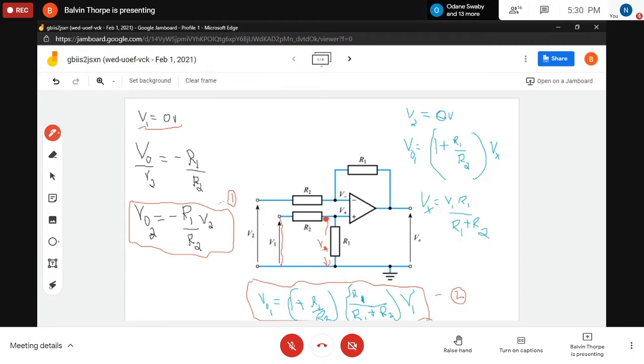We have looked at the inverting amplifier already. And if you can recall, the inverting amplifier's output voltage would be equation 1, where V2 is what's going in. The gain of an inverting amplifier is minus the feedback resistor over the input resistor. So it means that it's minus R1 over R2. That's the gain. But the output voltage is the gain times the input voltage. Am I correct?